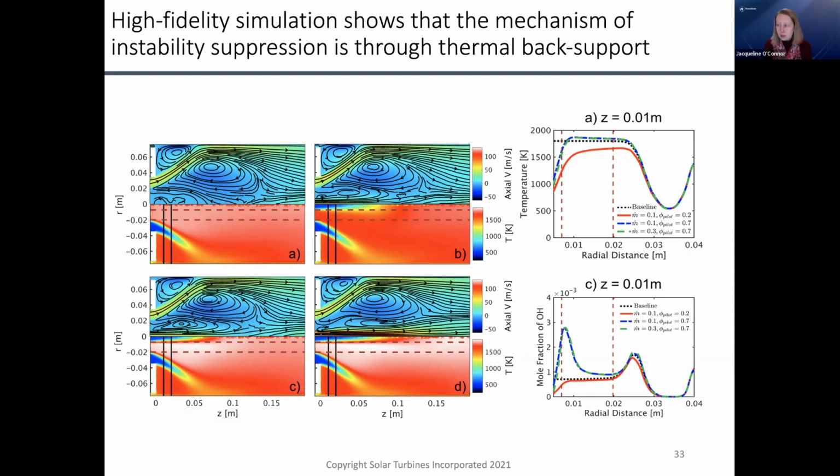But that's why these fundamentals are really important. It's not the level of hydrogen that matters. It's the flame shape, the shear layer receptivity, the stretch sensitivity of the flame, right? You can translate hydrogen level to these more fundamental coupling parameters and then see why in some cases hydrogen makes it better and in some cases hydrogen makes it worse. But there is a growing really nice body of research, including by several people on this call, who are looking at hydrogen and the effects that it has on thermoacoustics. So that's definitely of interest.